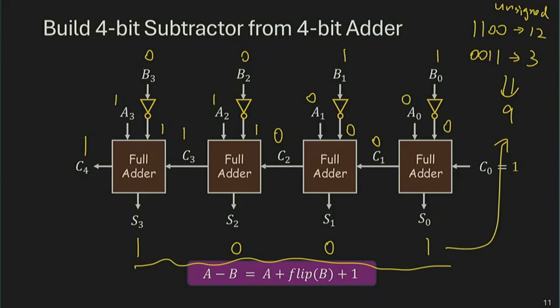This is actually the beauty of the connection between binary and Boolean algebra. In binary, we can develop addition and subtraction algorithms. And as it turns out, you only need to build one copy of a 4-bit adder to do many things: unsigned addition, two's complement addition, and also unsigned subtraction.